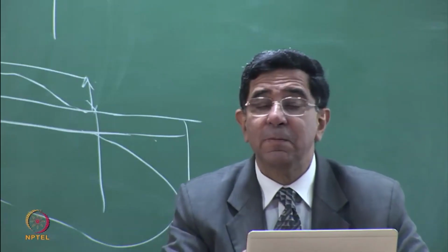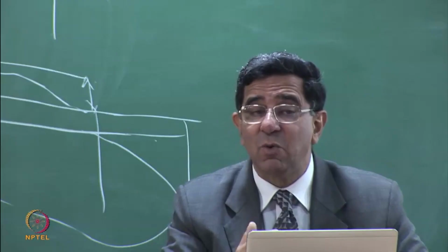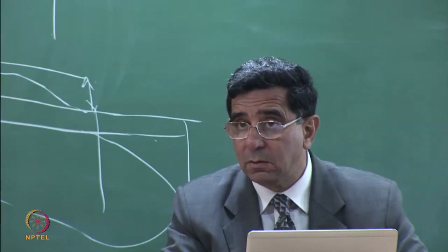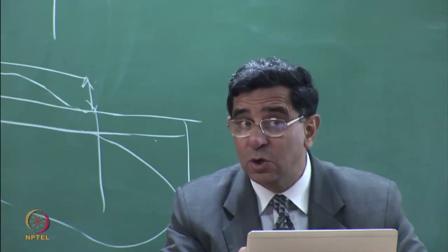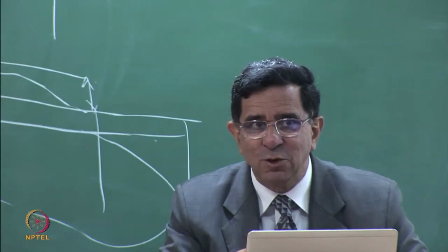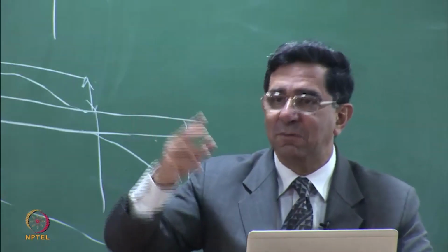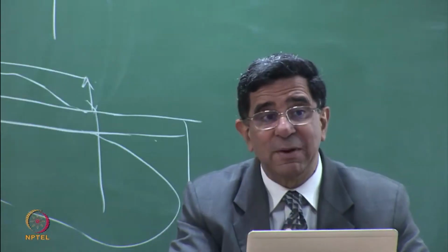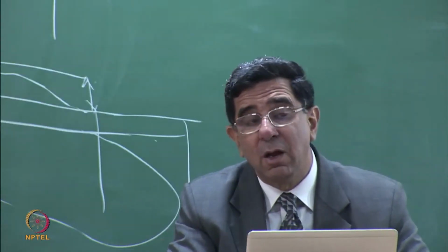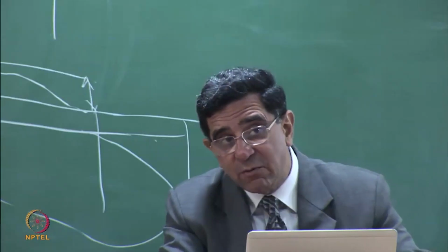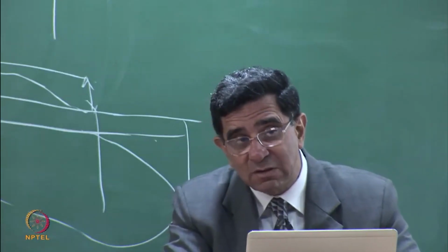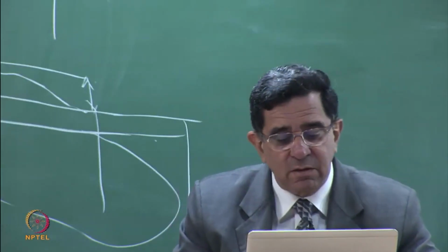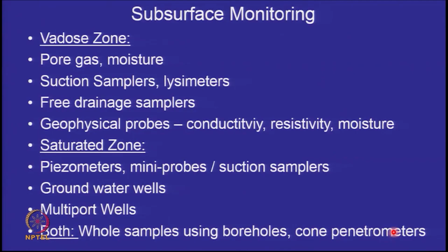All that was applicable for foundation design applies, but nothing should chemically change. While you're taking out the sample, the gas should not escape. If you're taking out the sample, the water should not escape. So you should be able to keep it whole. So whole sampling requires very careful sealing of the sample as soon as it comes out. Okay. So whole sampling down the borehole or using cone penetrometers.